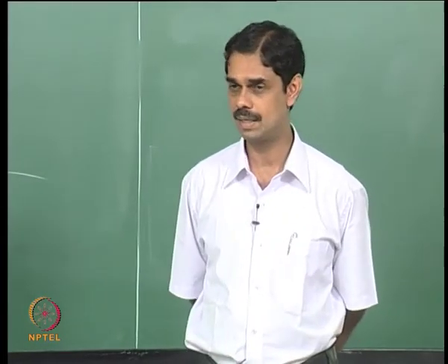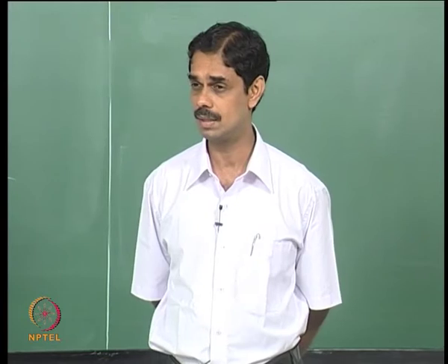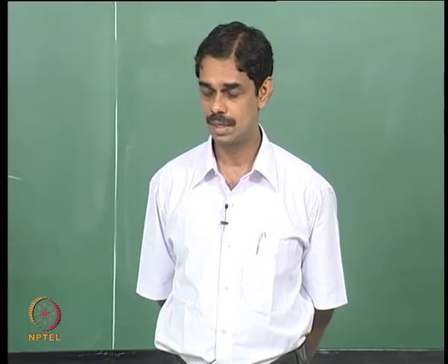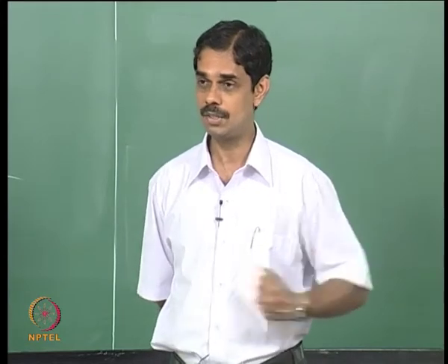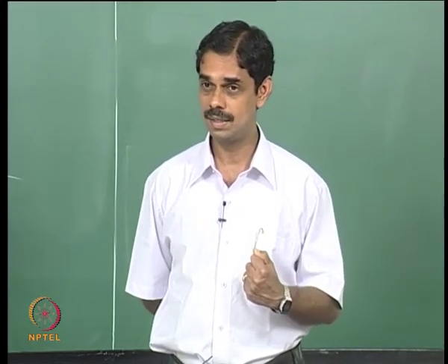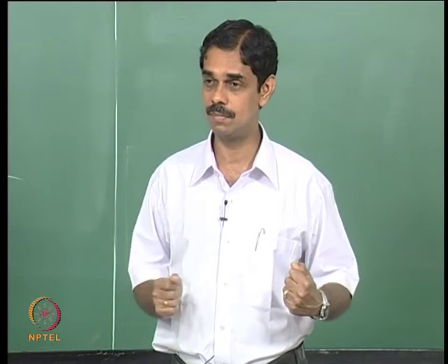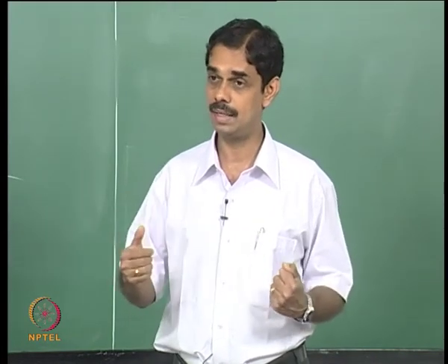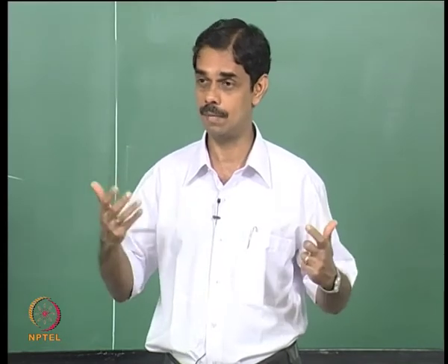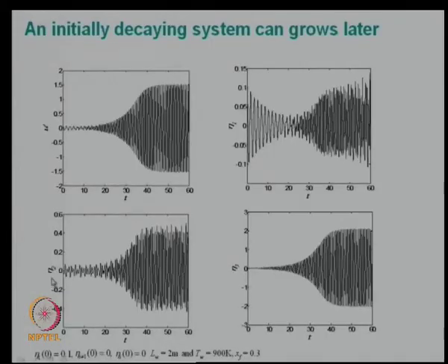He would be working it under third mode, 200 and something hertz, and it's a bluff body combustor, so the position of the bluff body is very important. With a sleight of hand he will change the position of the bluff body, and this mode will die and the other mode will come up. So you can see here the evolution of the velocity. It is actually a decaying system here, some mode is dying. Here in this case some low frequency mode is dying and then a high frequency mode came.